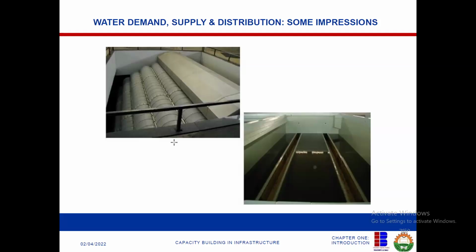Then with iron 3, you can see it becomes turbid, it becomes suspended, sort of. Then if you put in a flocculant, the appropriate one, which is always calcium carbonate or calcium hydroxide, it coagulates. When it coagulates, it forms lumps. Then you can easily use a filter system. Either use a sand filter, a membrane filter, or whatever filter system you have that's cheaper, accessible, and feasible. You now separate the suspended solids.